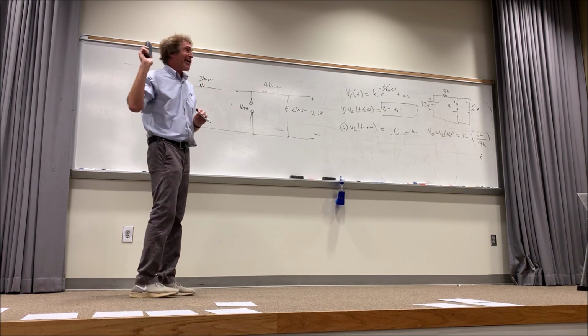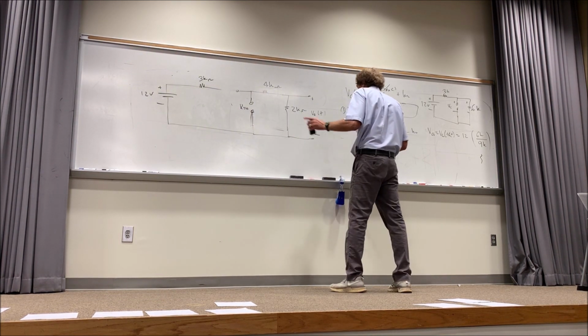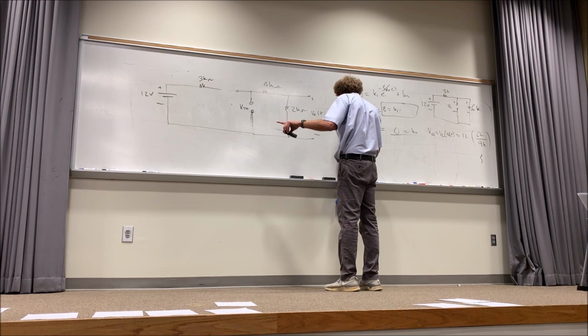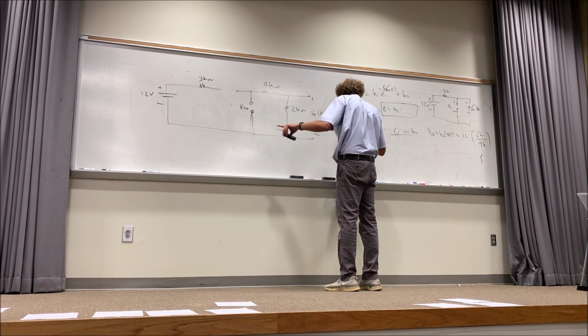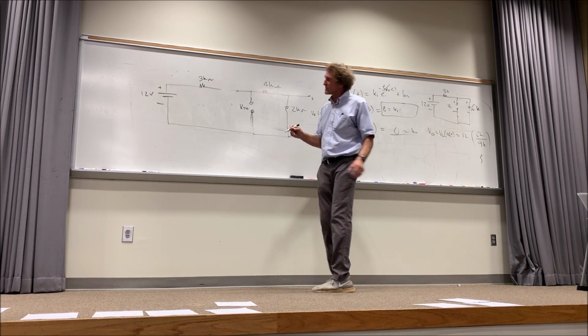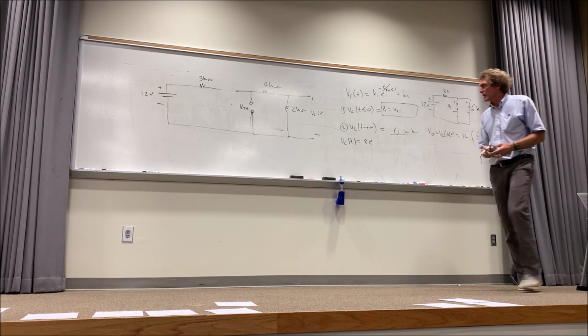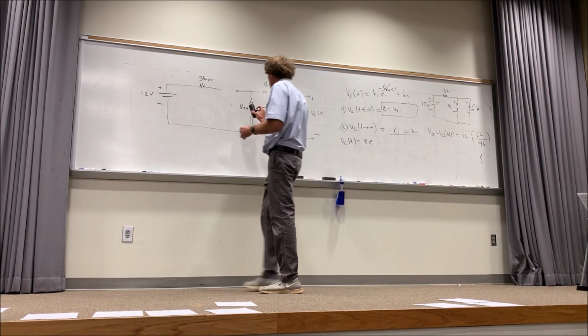All right. Now, we got R Thevenin as 6K. So what is our final equation? VC of t is equal to 8, right, times e. I didn't put a value for C in there, did I? For this one, C is 100 microfarad. I'll draw it back here.